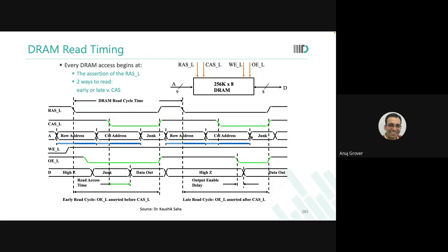So, DRAMs or main memories are designed to be very, very large. And just one DRAM chip cannot hold that kind of capacity. Because if you try to bring all that DRAM in one chip, then the yield of that die will reduce. Area would increase so much, and yield is inversely proportional to area. You cannot have a very large die. So in every DRAM package that you see, there are multiple dies stacked one over the other or stacked next to each other. All of them accessing the same output bits or same input bits, whichever we get.